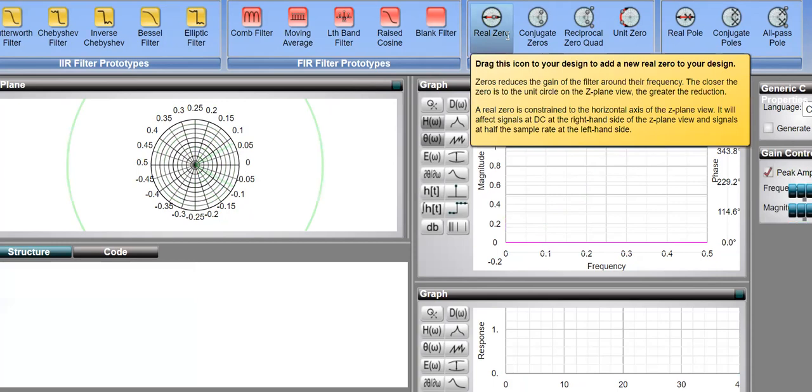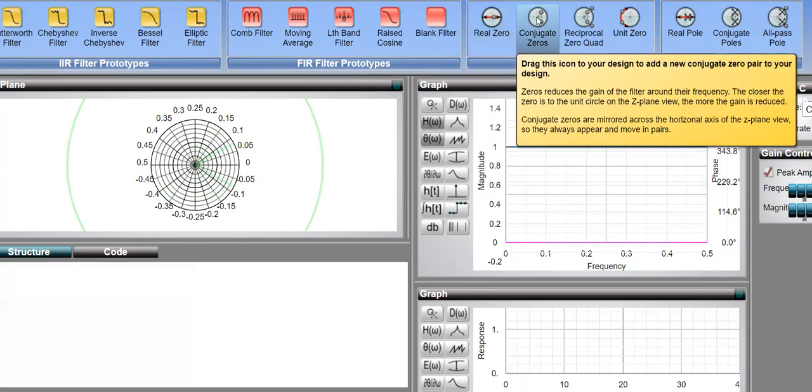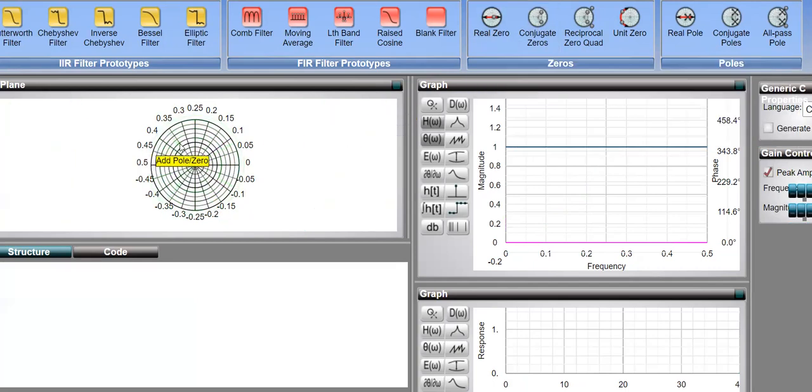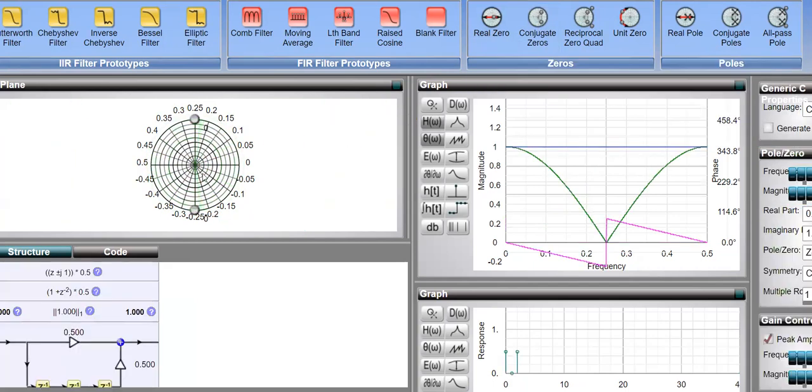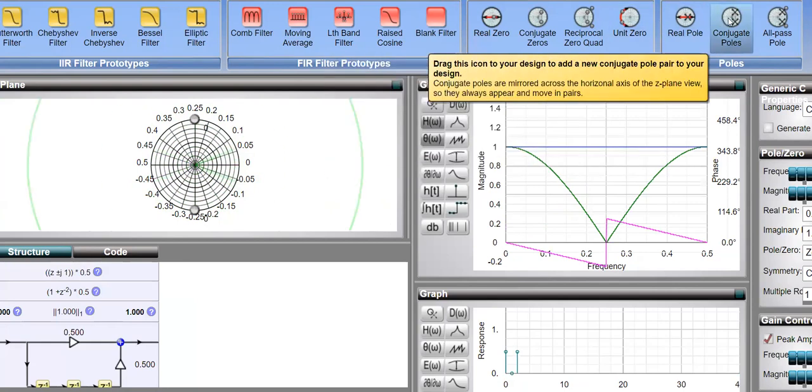Now for the notch stop band, for that one we can put conjugate zero locations, because we need a notch here, so that is obvious. And what about the pole? You need to find a pole location.